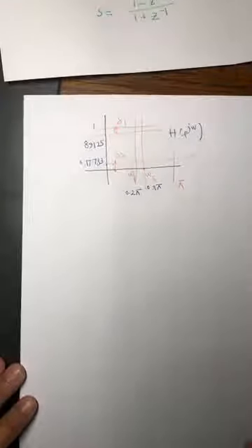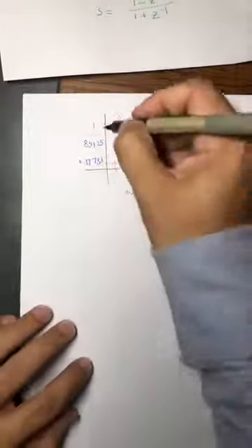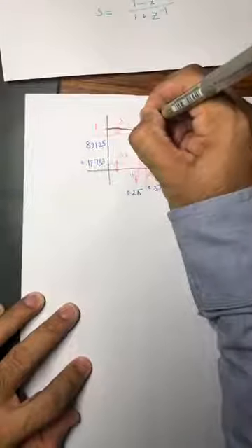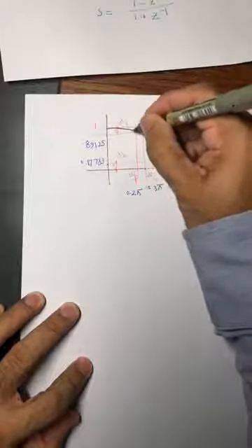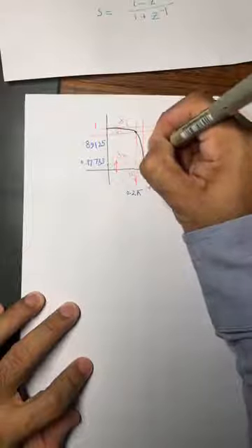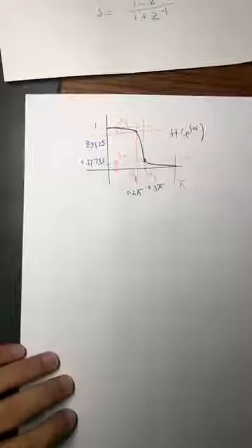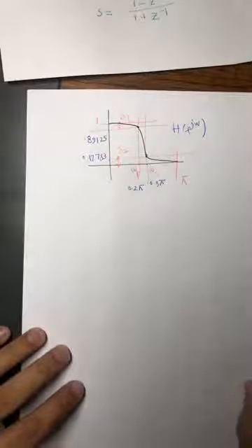So this is the question, and designing means you need to give an H of z for these specifications, something that fits. If it is Butterworth's, it is a monotonically decreasing function passing from this point, and then going down like this. But first you need to convert these specifications into capital omega specifications.